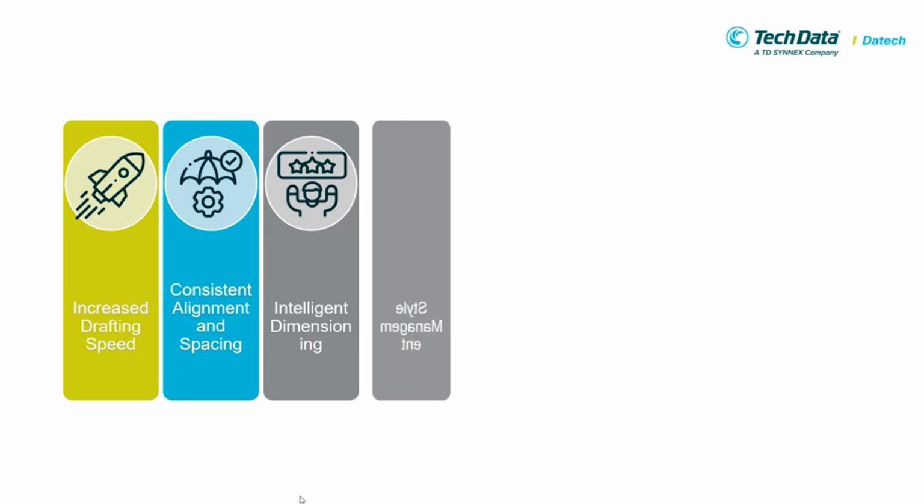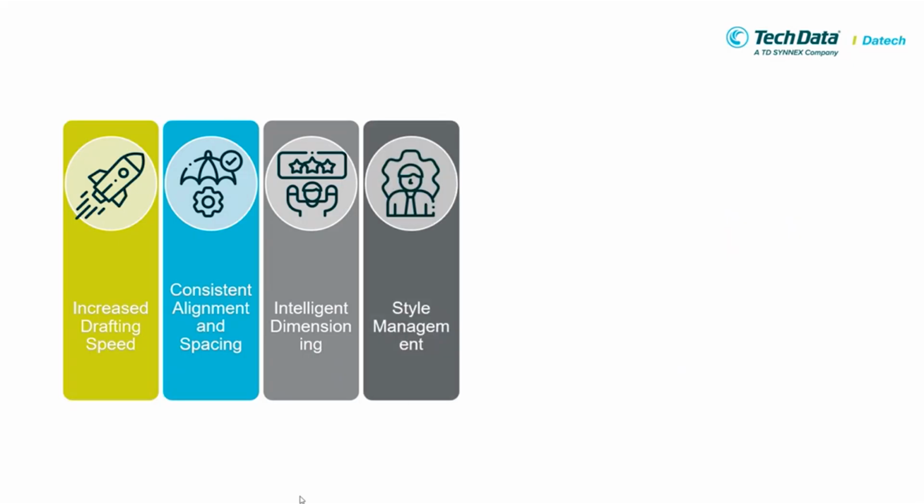Style management. You can rearrange existing dimensions into new styles, from chain to baseline, without deleting and redrawing them. This flexibility is ideal for adapting to different drafting standards.